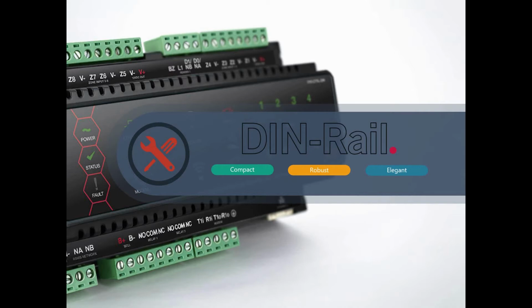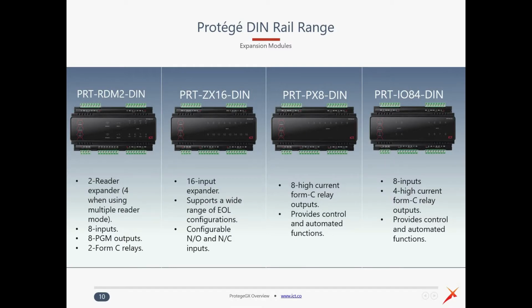All of our modules are configured for standard DIN rail mounting and clip easily into any DIN rail cabinet for easy and compact installation. When expanding a system, each access control expander offers up to 2 doors of expansion with the capacity to do up to 4 readers, 2 in and 2 out, as well as an additional 8 zone inputs, 8 PGM outputs, and 2 Form C relays. If you need additional inputs or outputs for additional intrusion zones or elevator controls, input and output expanders can also be added to the system as your needs expand.